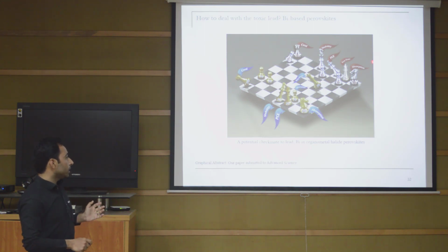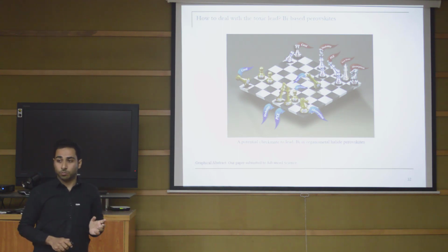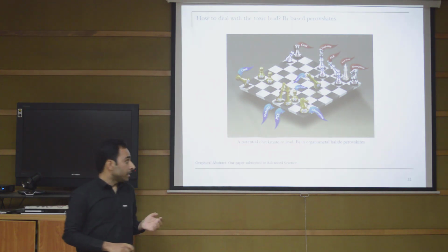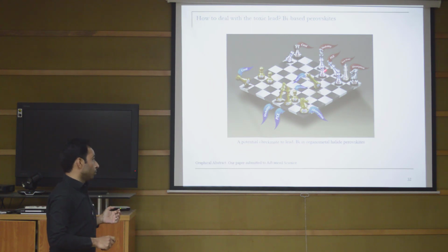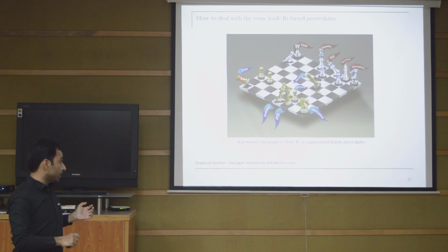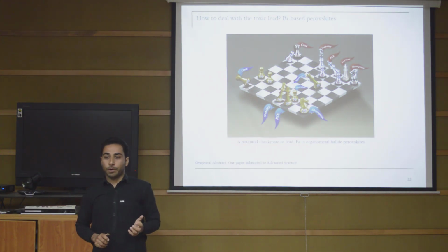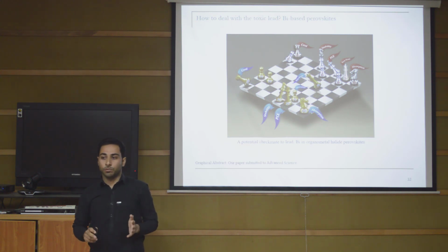They are non-toxic, they have comparable absorption properties and other optoelectronic properties, but there is one problem with this material. Their PCE is extremely low. It's about 1% only. On the other side, all the things are in favor of this, but one thing that is standing tall is the PCE of the lead-based perovskite material. It is about 25%, so 1 to 25, it's a huge difference.